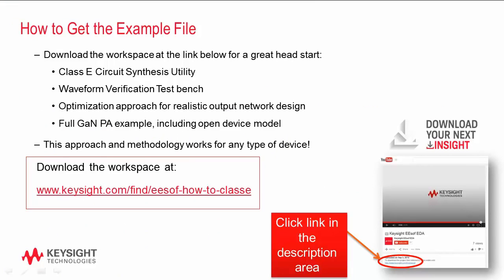And there you have it, a Class E power amplifier from concept to circuit design. I want to emphasize that this is a starting point for Class E PA design. There's still a lot more to consider. For example, you might need to think about coupling, stability, and design sensitivity, or maybe you'll want to investigate how to make the bandwidth wider, in which case I think doing a refined load pull is a very sensible approach. Keysight has some great YouTube videos on all of these topics too.